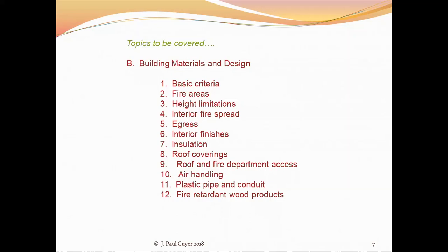And then there is another hose that typically, and I'm describing a multi-story building now, there is a connection typically on the outside of the building where the fire department connects a hose to the output of the pump on its pumper truck. The other end is connected to a fire department access fitting on the outside of the building, and that fitting is connected to typically a vertical pipe that runs the full height of the building.